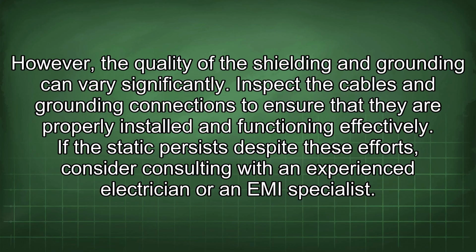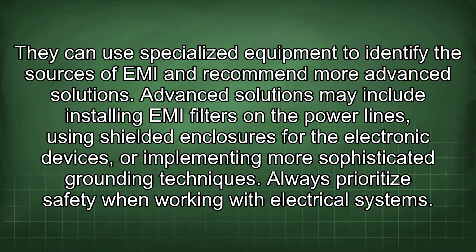If the static persists despite these efforts, consider consulting with an experienced electrician or an EMI specialist. They can use specialized equipment to identify the sources of EMI and recommend more advanced solutions. Advanced solutions may include installing EMI filters on the power lines, using shielded enclosures for the electronic devices, or implementing more sophisticated grounding techniques. Always prioritize safety when working with electrical systems.